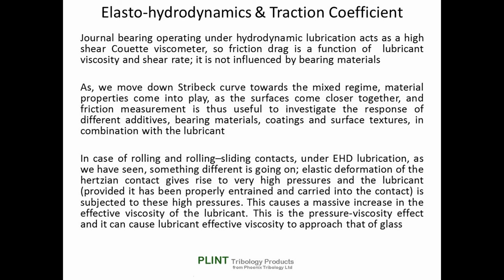In the case of rolling and sliding rolling contacts under EHD lubrication, something different is going on. Elastic deformation of the Hertzian contact gives rise to very high pressures, and the lubricant, provided it has been properly entrained and carried into the contact, is subjected to these high pressures. This causes a massive increase in the effective viscosity of the lubricant. This is the pressure viscosity effect, and it can cause the lubricant effective viscosity to approach that of glass.